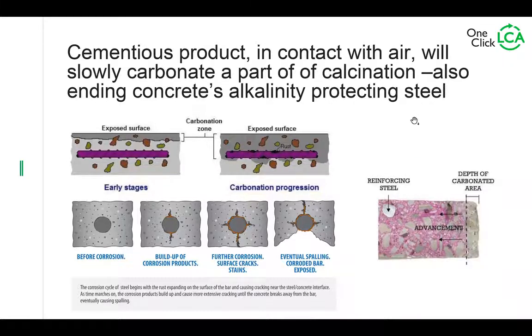But it's not a desirable characteristic in general because concrete is highly alkaline, and the absorption of carbon dioxide is a bit like, you know, drinking Pepsi, it's acid. So it's reducing the alkalinity, and when the alkalinity is reduced enough, it stops protecting the reinforcement steel, and it can lead to the elements cracking.